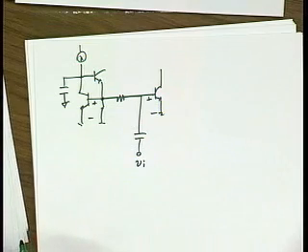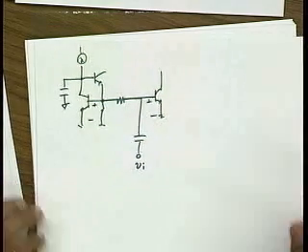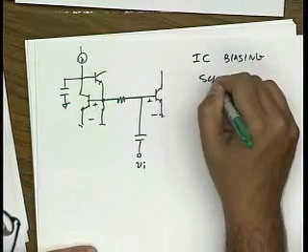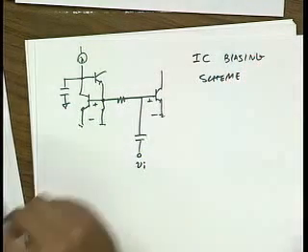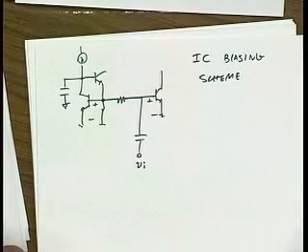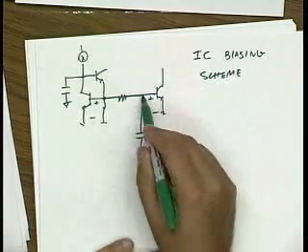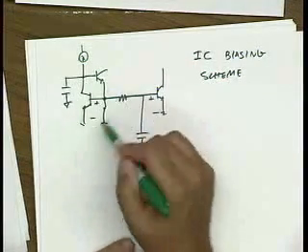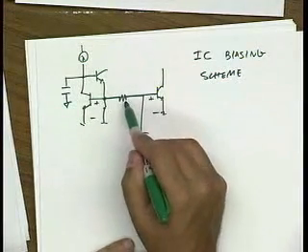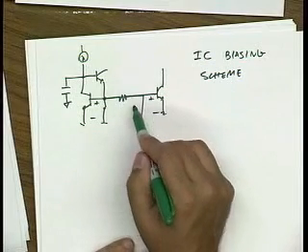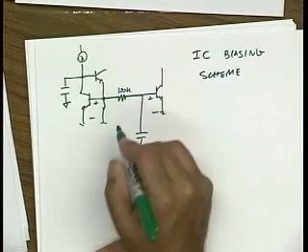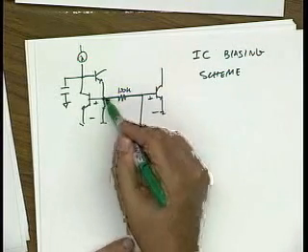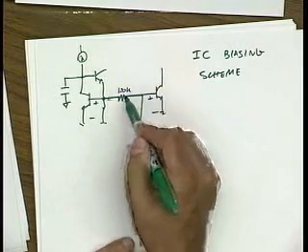Now there's other kinds of, so this is an IC biasing scheme. Yes. Could you just explain the function of that resistance and capacitance once again? Sure. So this resistance is there because I don't want my input signal to modulate this. I want this to be constant. So this resistor tends to reject that. So it introduces a large, this might be 100K. So that signal that reaches here gets attenuated by the input impedance divided by 100K.